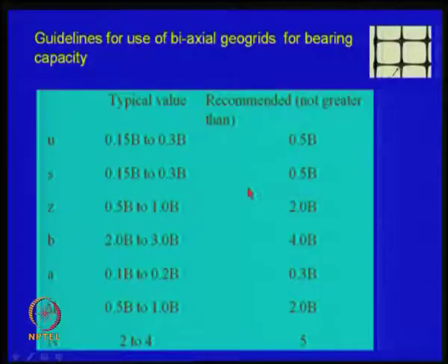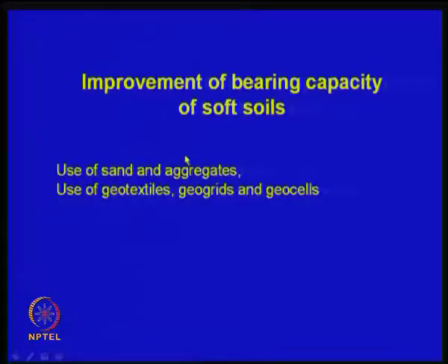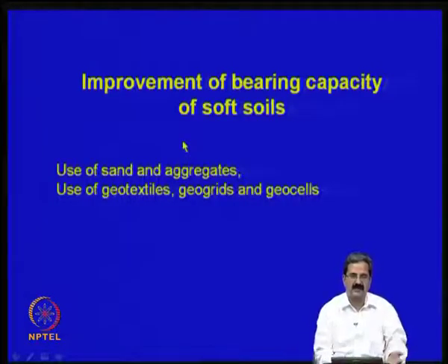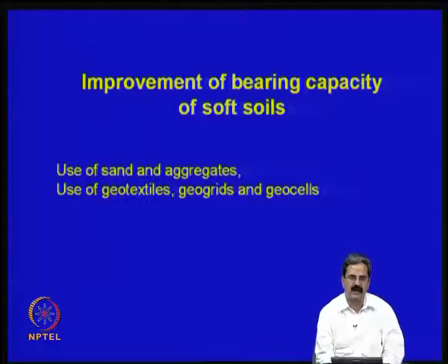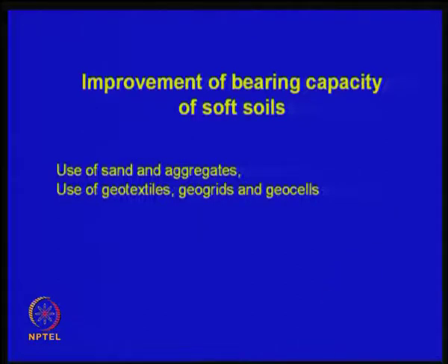So, additional information on this would be that we will handle what you have seen in the case of soft soil, the sands, how the bearing capacity could be improved, and the bearing capacity could be improved, as I just mentioned, because of the actual response of the reinforcement element. We have tensile force developed, we also have frictional, because the tensile forces are developed because of friction and also the bond resistance.